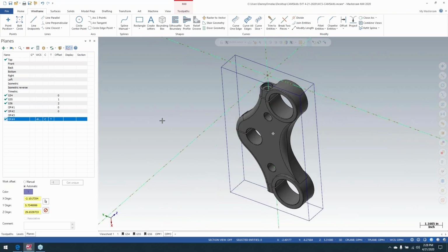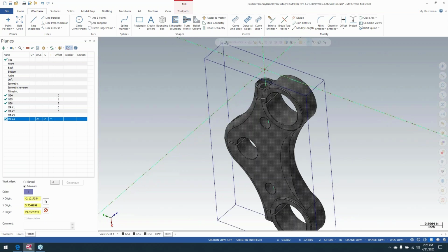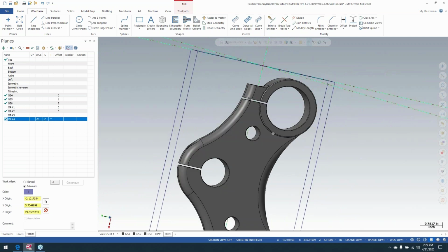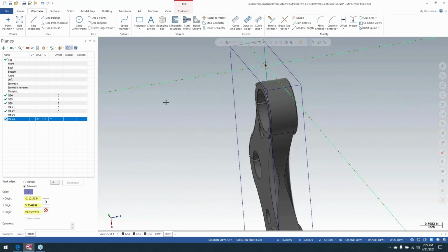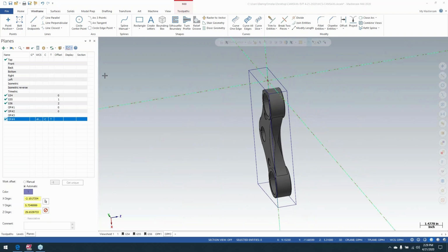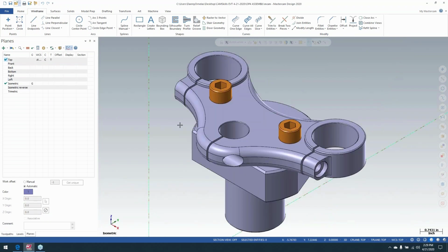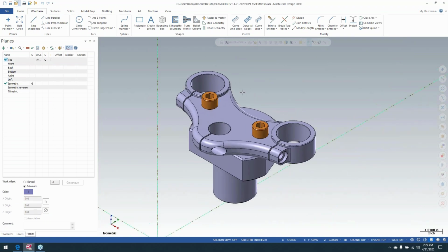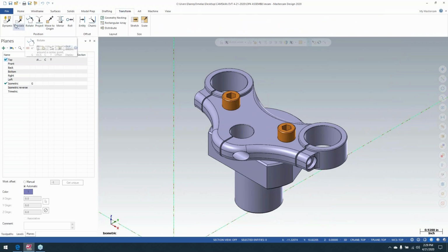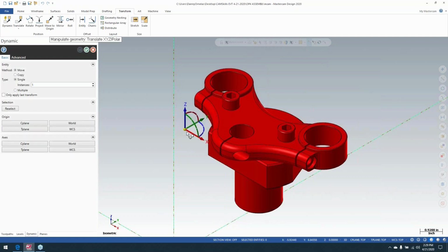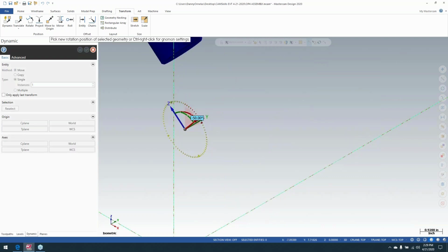All right. Well, good. So that's how we would get to these additional operations if you want to do the counterbore and then do the slot here. But what I do have is another option for the fourth operation. I'm not going to save this file. For the fourth operation, we made a fixture to put on the rotary table. So here's the part that came in from SolidWorks. Just going to go ahead and move it around. Doesn't matter where I put my icon here. I'm going to just flip it over 90 degrees.